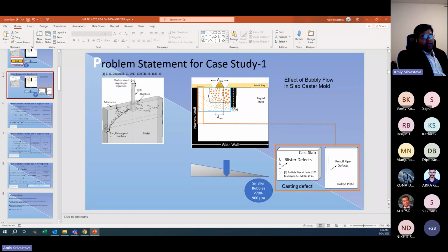Like 2 ppm. For slab casting we have an equipment called Hydris. In my previous company we had this equipment, and we were measuring the hydrogen content of each heat, and also in the tundish and in the mold. We have to maintain the hydrogen content, otherwise it can lead to hydrogen related defects, but those defects are different from this defect. Here we are only injecting argon, that's it.